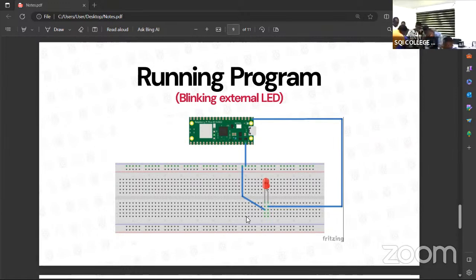No, this is not good. The exercise is to make sure you are blinking the LEDs one after the other. Don't blink them at the same time. If you connect it that way, everything will come on at the same time and go off at the same time. That means every LED's positive side will have its own GPIO pin.